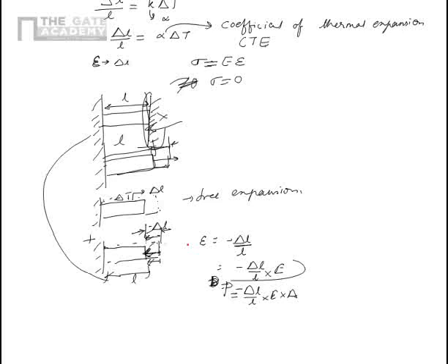Similarly, if there is an applied force which causes internal reaction, then obviously there is a stress. There may not be any strain because the length doesn't change. The strain being a geometrical entity, the change of length, is not there, but stress, which is the reaction to an externally applied agency, can still be there.